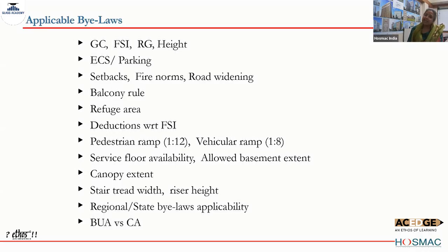And finally, the height of the building will determine the setbacks. The equivalent car spaces is a concept which is applicable in northern India, but not in Maharashtra. So again, like I said, state-wise, these will differ. And we have the parking norms in Maharashtra, in Bombay particularly. Let me not say Maharashtra because in Nagpur it was ECS. So parking is in Bombay.